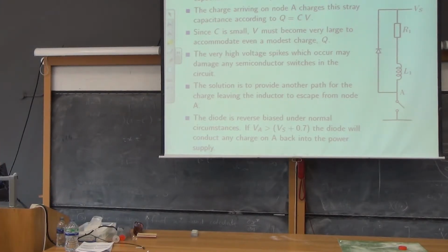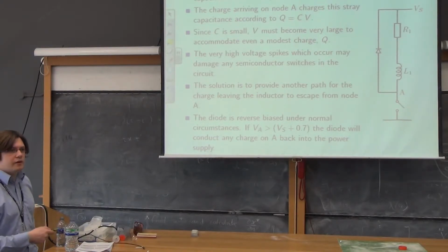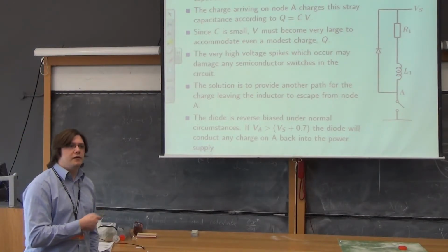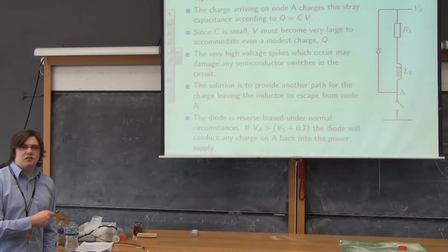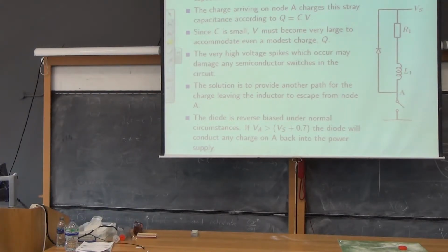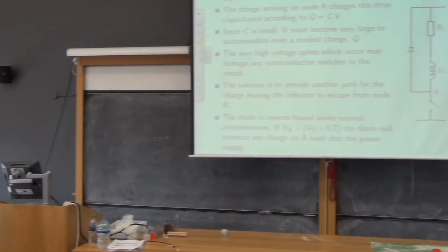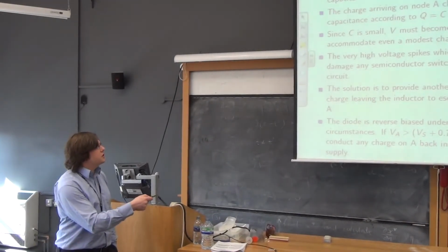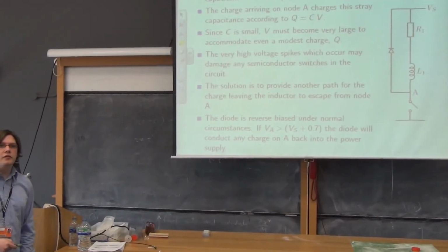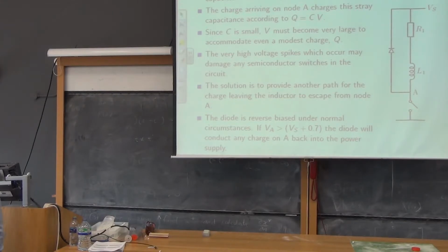And there will be an exponential decay because we've got an L and an R, so we'll have a first order circuit, and the current and all the voltages around it will decay as an exponential according to the same sort of laws that deal with RC networks. If you want, you could put an extra resistance in series with the diode to adjust the time constant, and you might want to do that if you've got to pass some sort of EMC specifications. Some of the questions in the problem sheets do have a resistor there, and others don't.